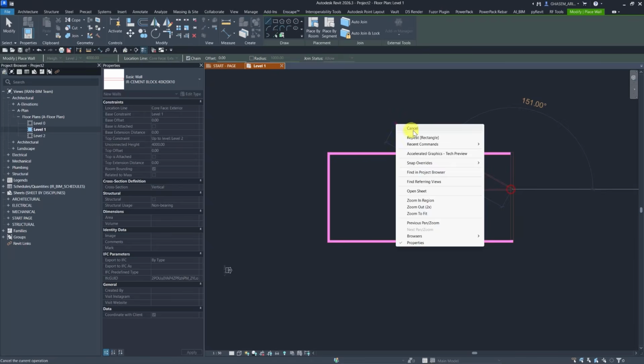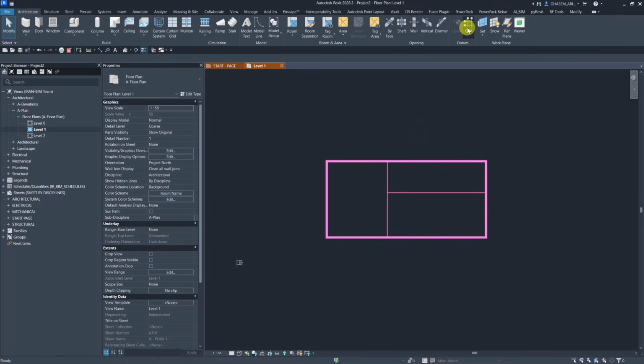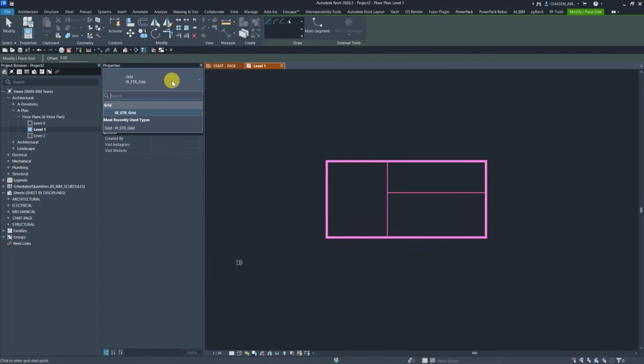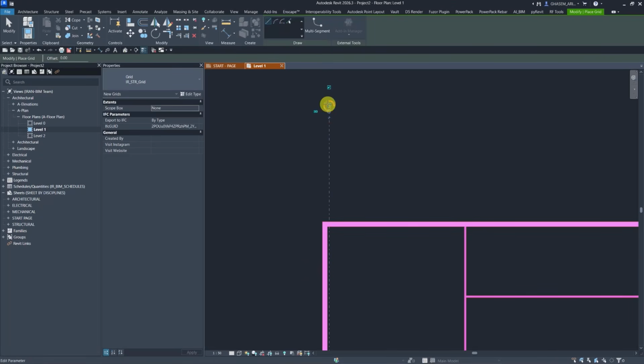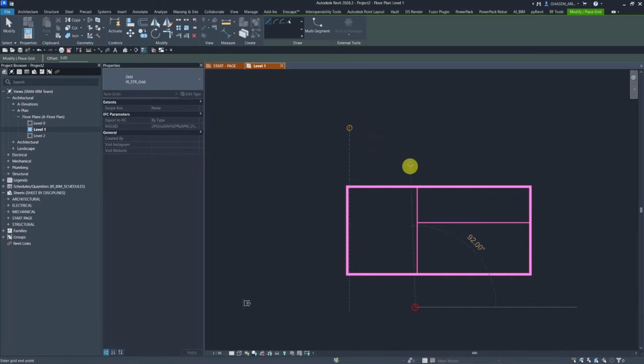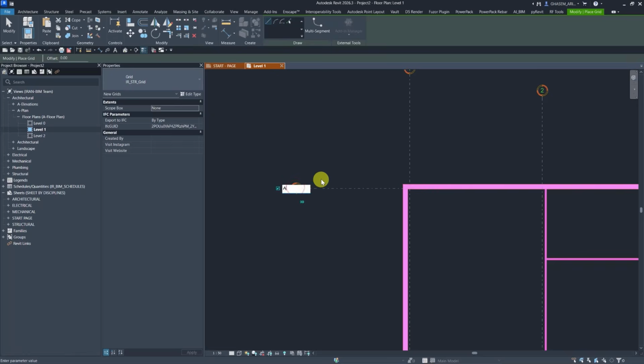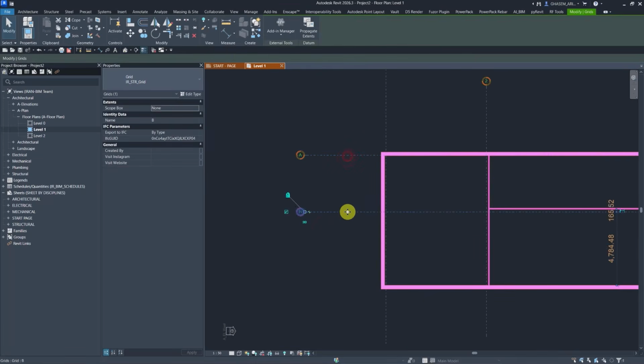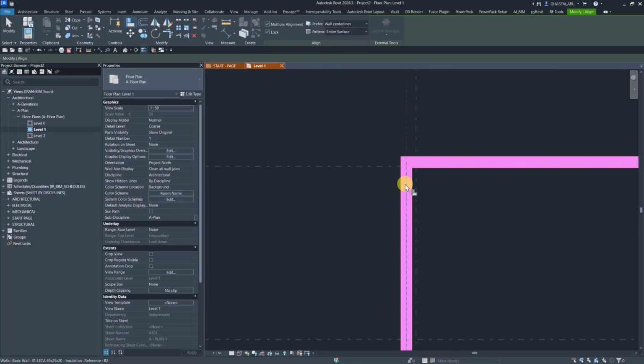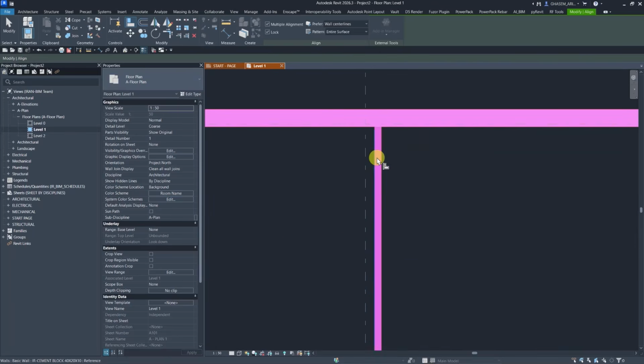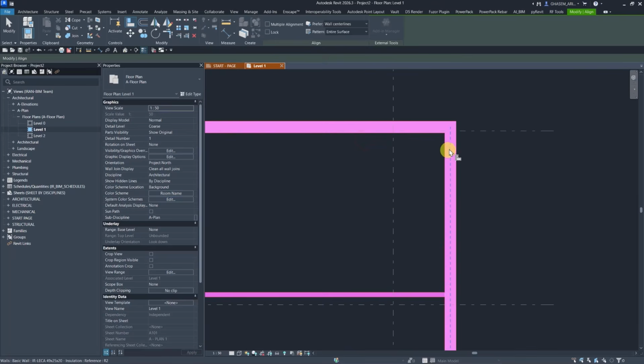As another example on another item, let me work with axis. As you can see, I just need to select the item and start setting my axis or grid based on what I need in my project, and regarding their settings, well, they are all predefined or pre-specified, if you will. And in this case, by predefined settings, I mean, for example, the symbols, the line weight, even the line type, guys. Now, obviously, this way, not only working on a project would be extremely faster, but also, as I said before, it would be more professional.